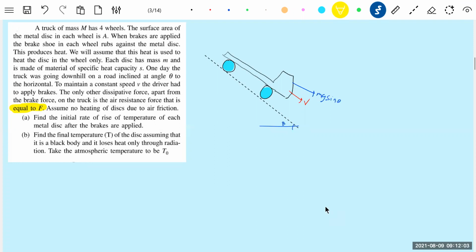Yes, you put on the brakes and the friction acts here such that it will be rolling friction. And the net work done by the rolling friction should be 0. So this is what happens. Now, the decrease in gravitational potential energy, what will it be converted to? There will be some brake shoes that will come here. They will apply the retarding torque, and in fact they will consume that energy.